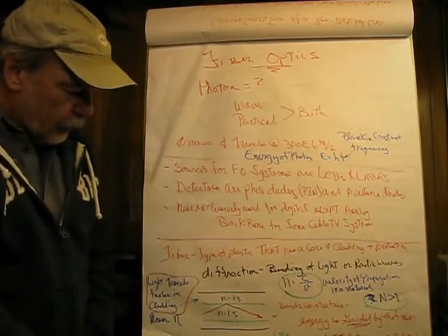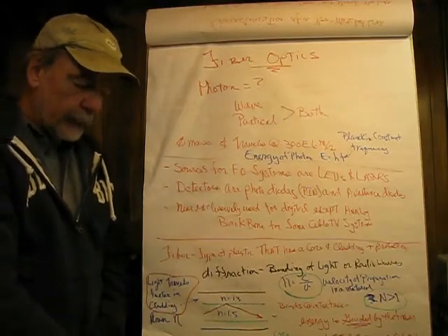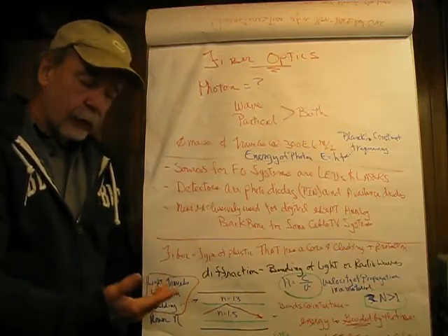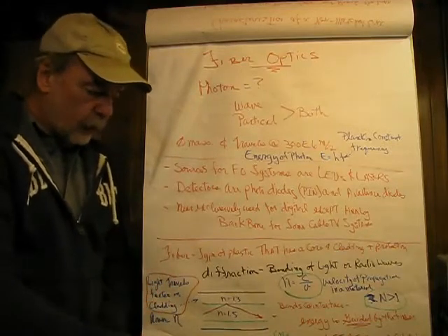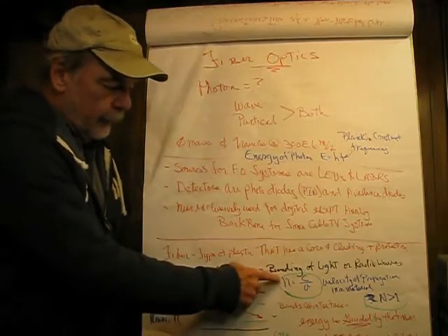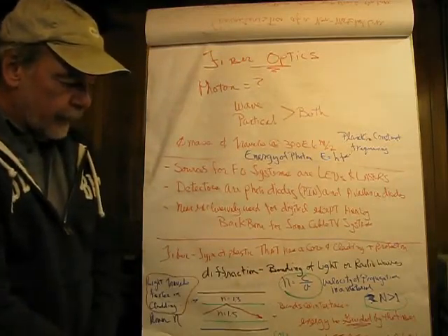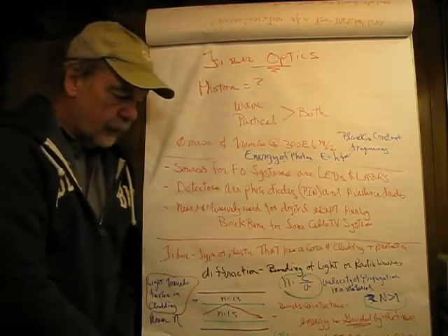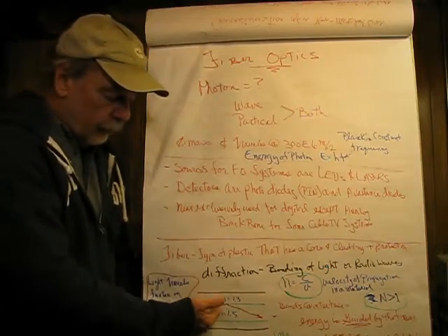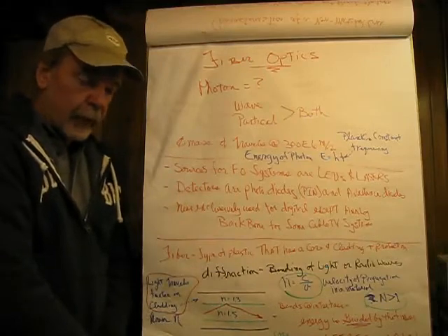So what this is called is total internal reflection, TIR, and it's what sits under the hood of why fiber optic systems work. So we have the N here, the index of refraction, and that's simply C divided by the velocity of propagation through anything, really.